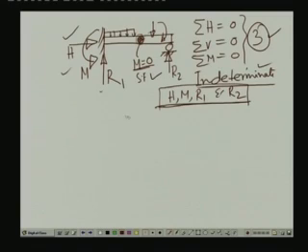So, in fact, as you can appreciate now, if you have an articulation introduced in an indeterminate beam where you have one additional unknown reactive force over and above the 3 reactive forces, then we can solve that, or the beam becomes determinate in that situation. Now, this particular articulation can be introduced in this form.